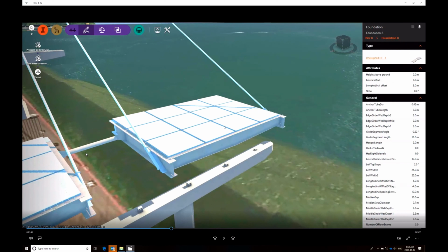Yeah. Okay, great. How do you handle profile views? Yeah, that's a good one. Developed elevations, you're talking about? Yeah, in Revit. Yeah, that is a workaround workflow where you export the bridge into Civil 3D and project it in the profile view.